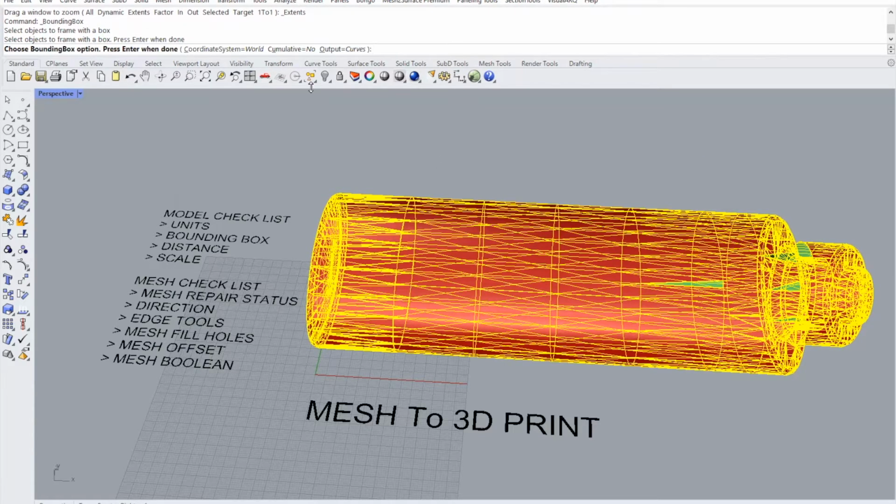Looking at this option here at the bounding box, it has an option known as accumulative. If you say no, then it will put a bounding box on the individual items. So I'll leave it as no. If you see a yes, you can click on this and change it to no, and let's give it a try.